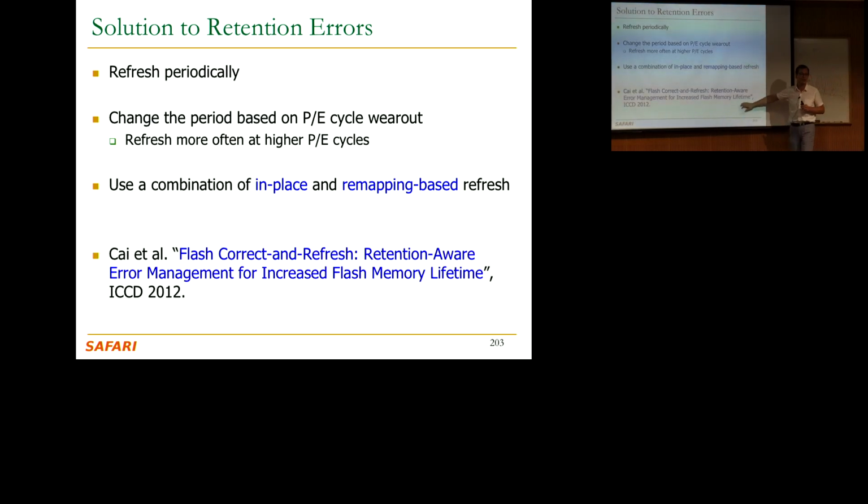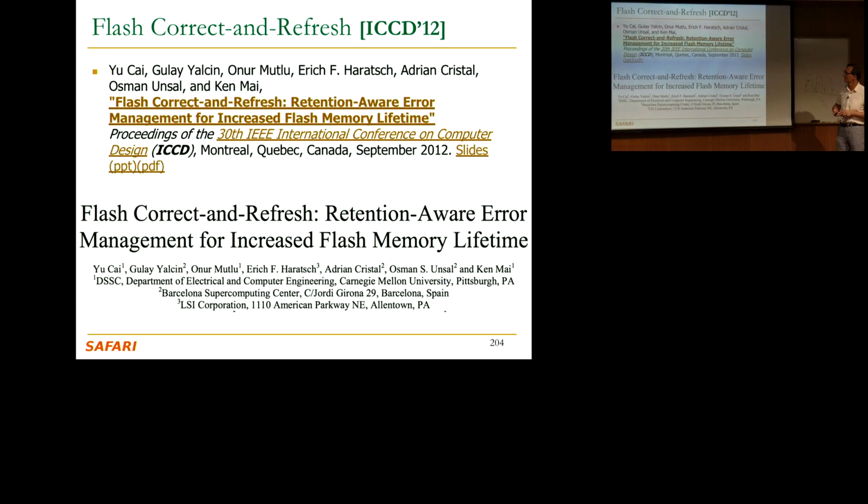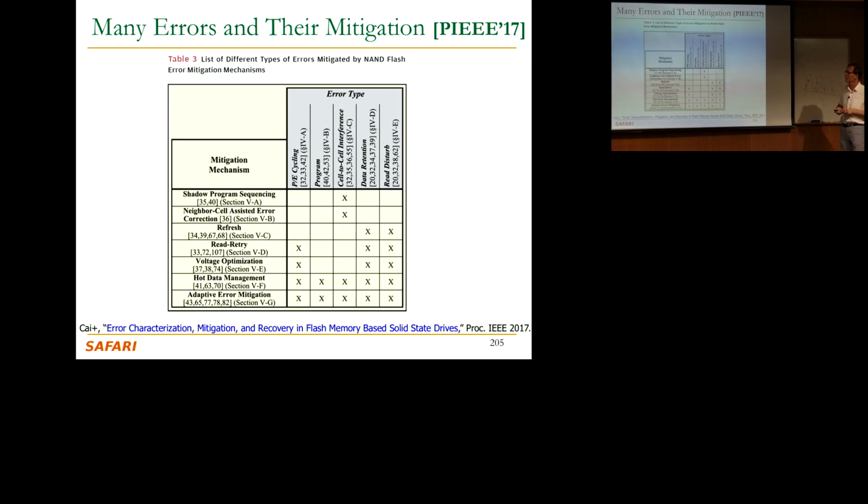And this shows that you could actually improve the lifetime significantly, like more than 47x or so, if you do this right. And as far as I know, all of the commercial SSD controllers that are employed in data centers are using this sort of refresh today. They need to, because they need to guarantee that endurance requirement. And if you're interested, this is the work.